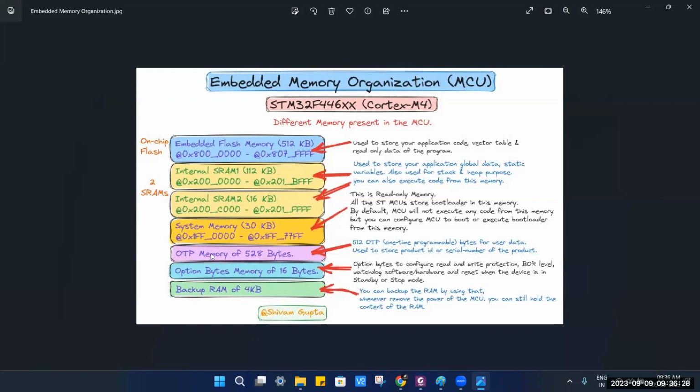Okay, because what I understood once from reading some STM32 secure boot articles is that write protection is used for protecting the bootloader from unauthorized changes by physical tampering. Correct. That is a read-only memory which you are talking about, the system memory. In OTP, the one-time programmable area, it is a very small area, in bytes, in which you can put some string, some serial number data. They have even put a limitation on how much length you can put there. Once you set the bit, it will never change. And what you were talking about, yes, this is a system memory in which the bootloader is there, and they have made it read-only memory.